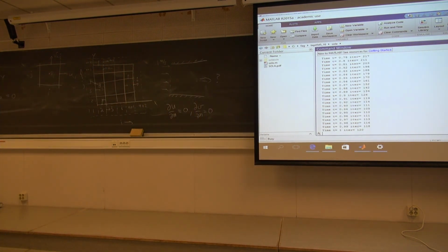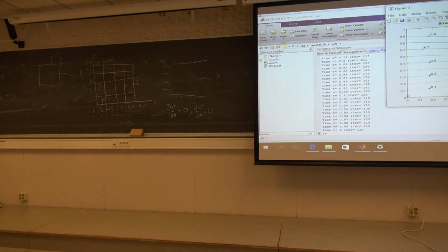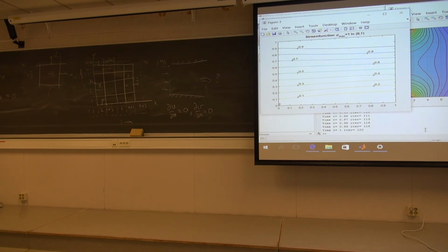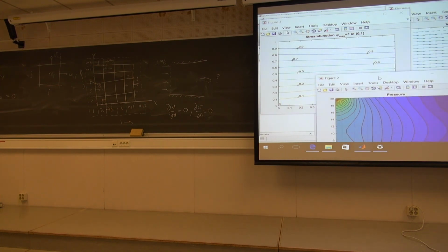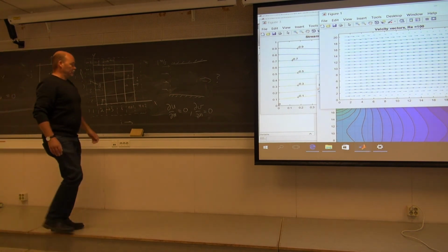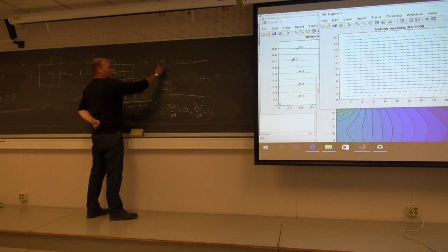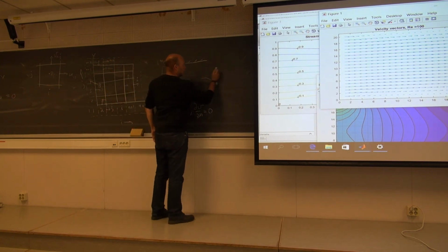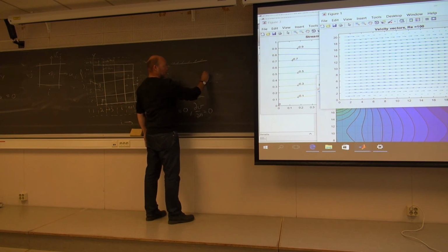For this problem now, the Reynolds number has been set to be 100. So this is probably not correct, but that's something you have to fight with in exercise number 1. At least here you see something that is not totally stupid. You send in a constant flat velocity profile. If this domain had been long enough, what should you get on the outlet? Well, you should have the laminar solution for a Poiseuille parabola.